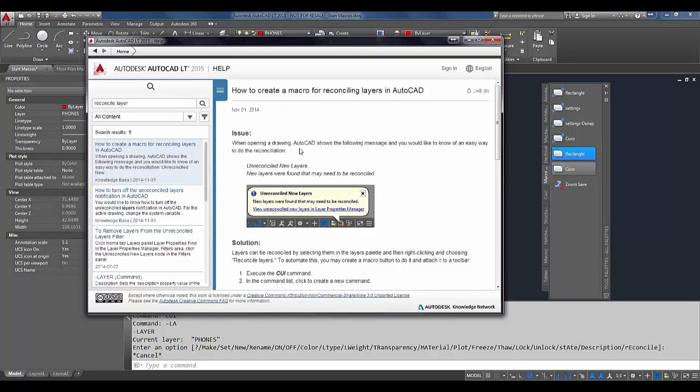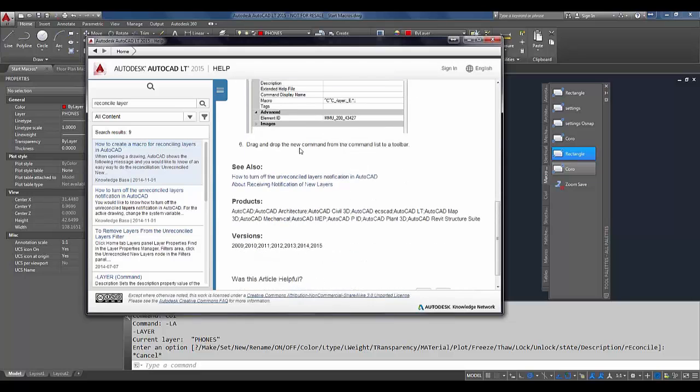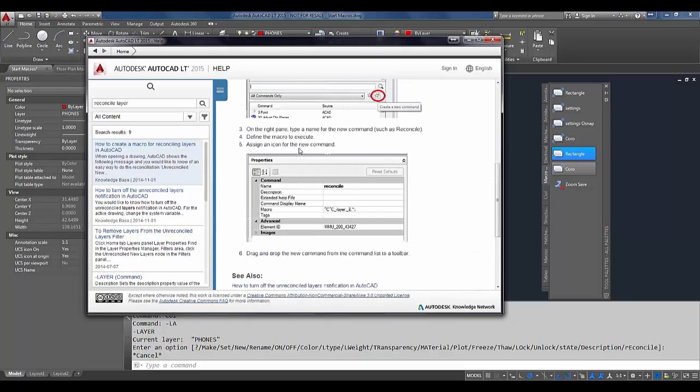And yep, how to create a macro. There you go. Look at that. Didn't even know that was there. Yeah. All right. And there it is, right there. Yep, and again, if you look down here on the command prompt, E is the capitalized letter of that option. That's what you want to type in your macro, the capital letter, whatever you would type at the command line to get to that option. Good one. Nice help file there. Yeah, it's a very good one.